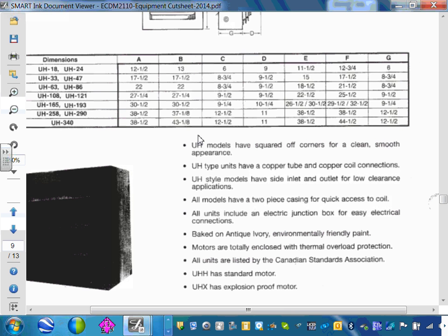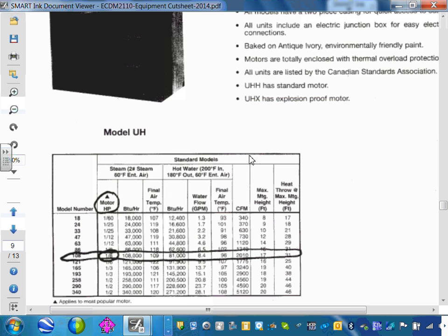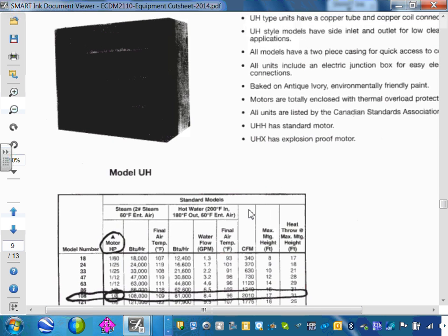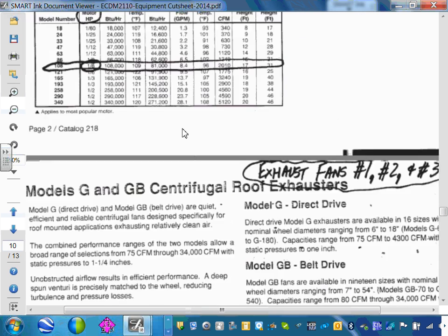They have a special heater just to heat that area, instead of bringing hot air. Data rooms need air conditioning, but you'll see with the receiving area, they don't want to bring the ducts all the way there. They just put a heater there to heat the area, just enough not to freeze, because nobody sits there. So they use them in the mechanical equipment.